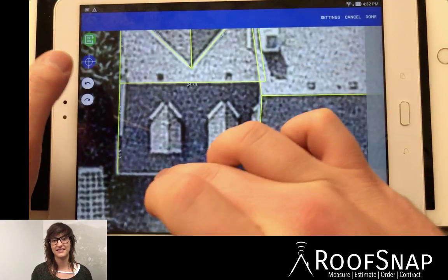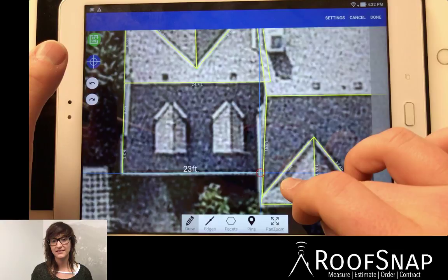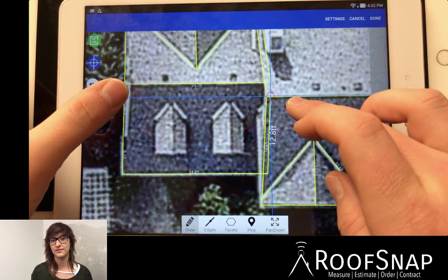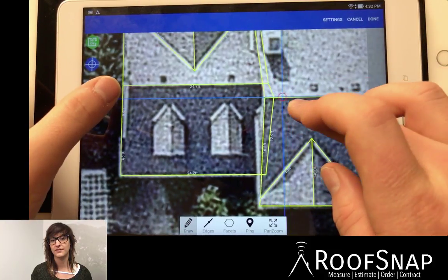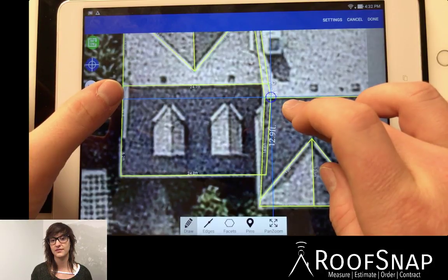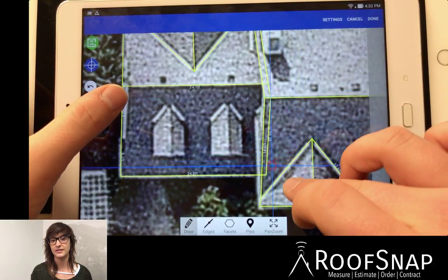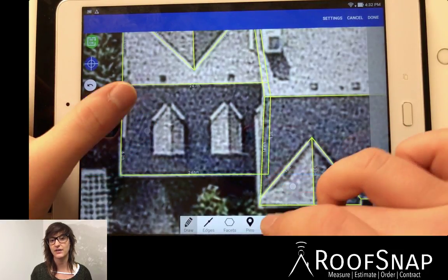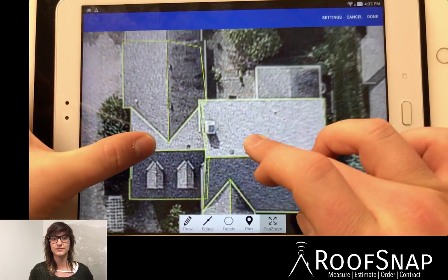Now where this eave had previously been connected directly to the rake, we are, once again, going to go past, draw up, and I like to actually split this and make this two lines, and then we'll just move it in a little bit, make it nice and about as even as we can. This way we're not connecting that bottom roof plane to the top, but separating those out, and when we tap on facets, now we've got that overhang.